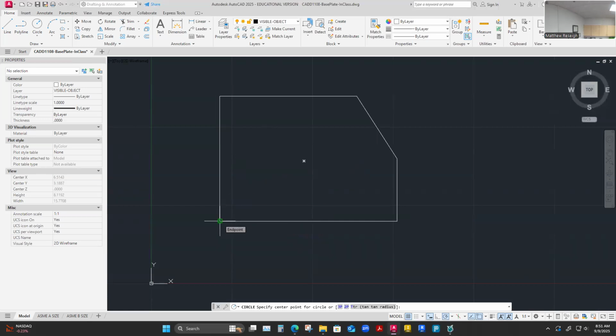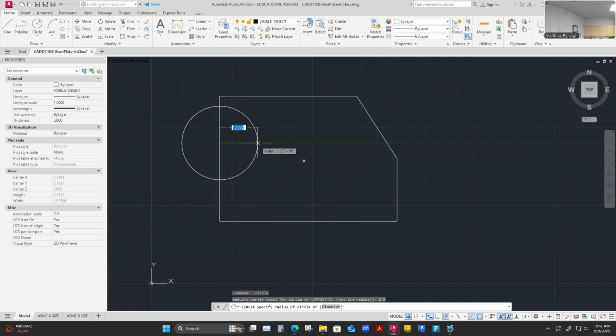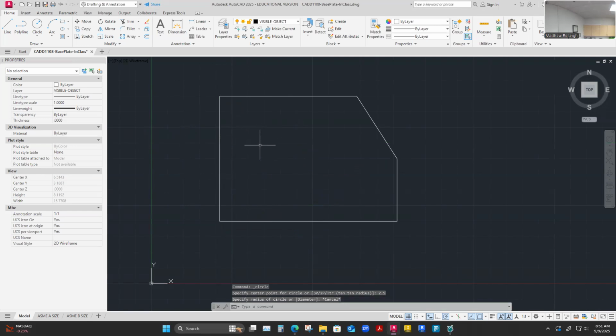And I don't have it. I think I can go up this way and toggle and say it's 2.5 inches over, but then it's going to lock me in as that being the center point. So it works a little different than how I do lines. This one might be a good candidate for building some construction work. I have a line with an endpoint right here that I can use as the circle center. So this is a good candidate for some construction work.